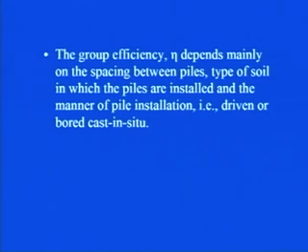The group efficiency eta depends mainly on the spacing between the piles, the type of soil in which the piles are installed, and the manner of pile installation, that is whether it is a driven or bored cast in situ pile. As you have seen, we have already discussed all these aspects one by one in detail.